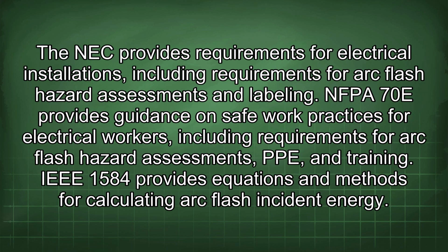The NEC provides requirements for electrical installations, including requirements for arc flash hazard assessments and labeling. NFPA 70E provides guidance on safe work practices for electrical workers, including requirements for arc flash hazard assessments, PPE, and training. IEEE 1584 provides equations and methods for calculating arc flash incident energy.